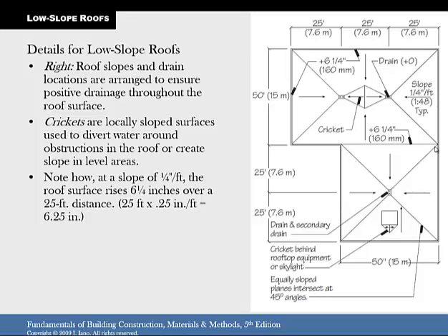Okay. And then C says if the roof edge can rise as much as 16 inches above the drain level, what is the maximum possible slope specified to the nearest 1/8 inch? So for that one, you would just say, okay, now my roof edge can be 16 inches above the drain. And you know that from here to the drain is 35 feet. So you go backwards.